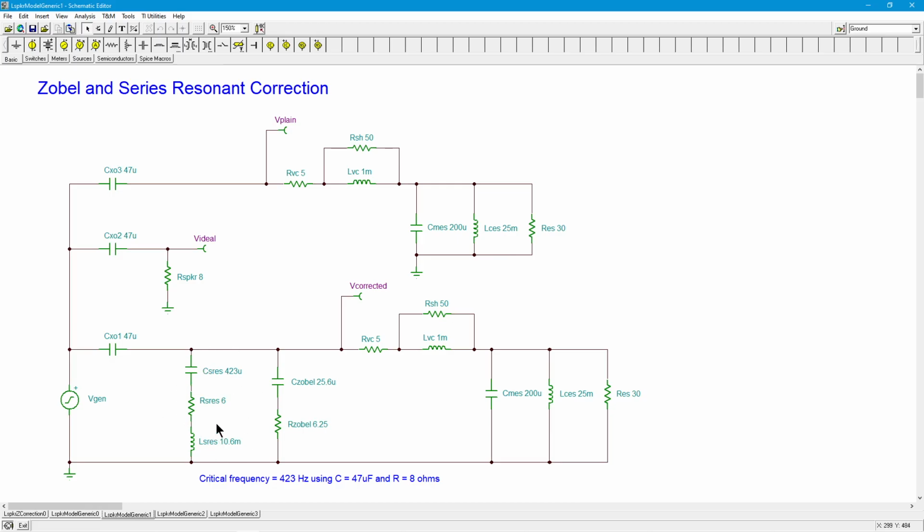So if you think about a series resonance circuit, it has an impedance that's sort of U-shaped. At really low frequencies, the cap opens up, so we get a high impedance at low frequencies. And then at high frequencies, the inductor opens up, so we get a high impedance up there. And right at resonance, X sub L and X sub C cancel each other, and all we're left with is the series resistance. So we have this sort of U-shaped thing. Well, that's the inverse of what the resonant circuit over here is giving us. So if I can throw this in, that should compensate for this. So this is going to be resonant around whatever Fs is.